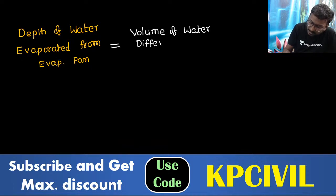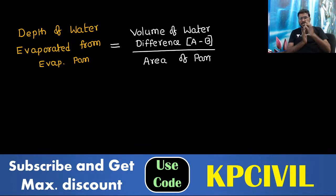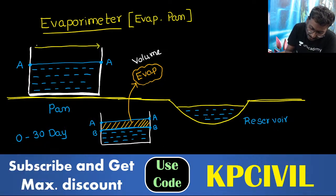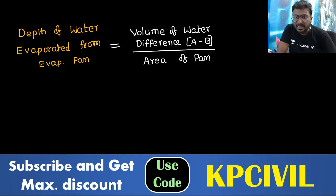The volume of water is the difference between A to B, divided by the area of the pan. So that is exactly the depth of water evaporated from the pan. You are measuring this volume, and the area of the pan, because we know the pan diameter. You can take the diameter of the pan as 1.2 meter. So this much volume of water, A to B, is evaporated from a pan with a diameter of 1.2 meter. So how much depth can we say now? The volume of water difference between A to B divided by the area of the pan.